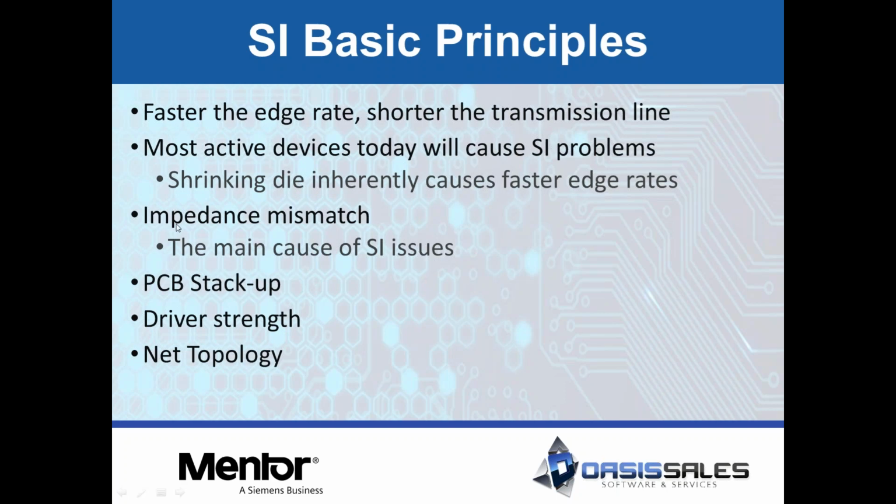Again, the main issue with signal integrity comes from impedance mismatch. All right, so the trace allowing the signal to go from the driver to the receiver end of the IC that you're using. You can't control the input impedance of that IC that you've chosen. It is what it is, but it may not match, obviously, what the output impedance of the driver chip is producing.